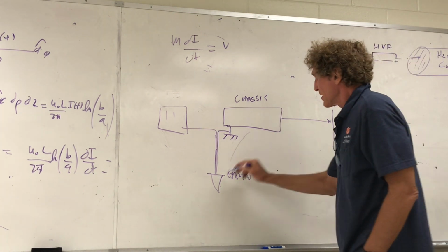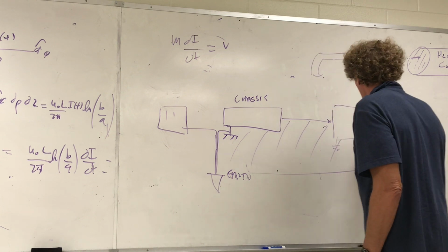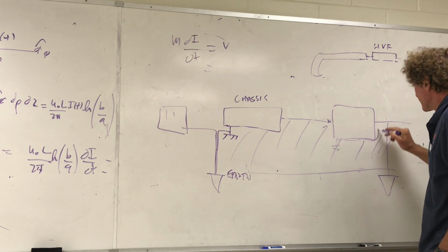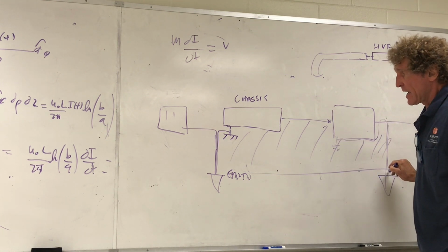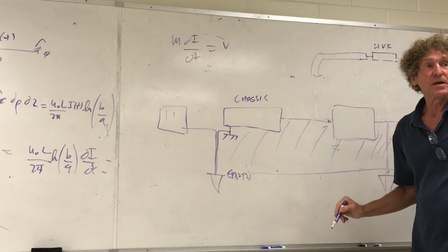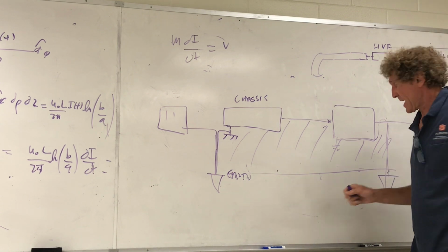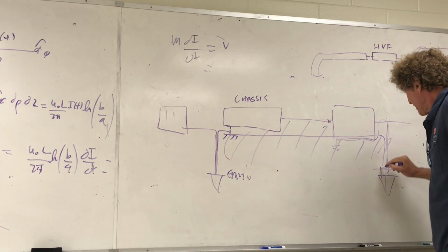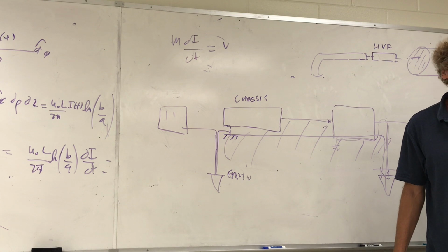I don't know what the area is, but can you see right here, we have a path, goes there, goes in through the chassis ground, come over here, into the chassis ground, back here. And what you end up having right here is something where you can get a ground loop easily. And what happens is it doesn't even go around there, it does this. Current goes up and then back down there. And that's the dangerous thing with any time you have grounds.